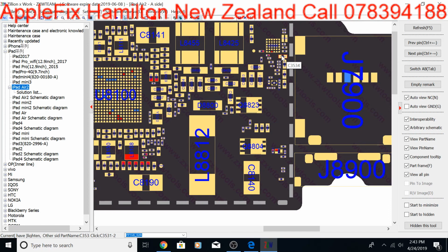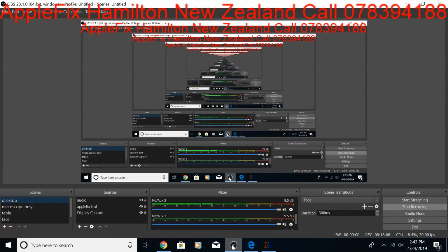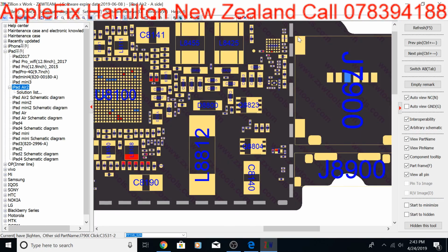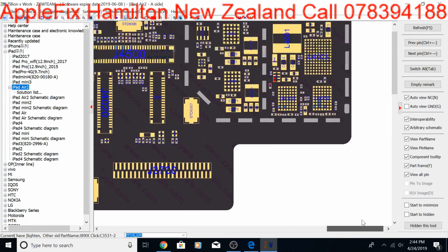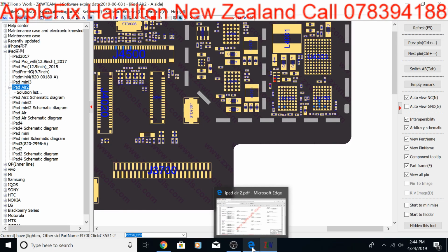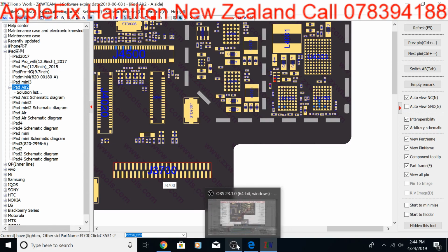And we found out one of these components is not stable, and on this one, which is the 3-volt line, there was no 3 volts, so we made sure this is the IC which is not working, which I'm quite sure. The other thing which can possibly be wrong is the charger, the cable which is connected, but the problem here was the current was intermittent, it was flowing, it was not flowing, so that most probably is the IC.